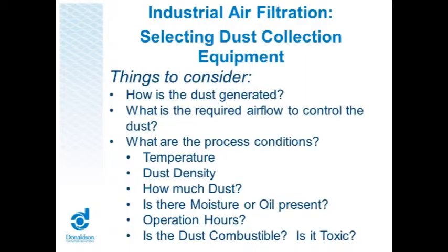It's pretty easy. You've also got the loading, is what we call it, or how much dust are you throwing at it. If I've got a welding process where one guy's doing 5 minutes of welding and 30 minutes of fixturing, that's different than if I've got 5 guys welding for an hour at a time and throwing a bunch of fume at me versus that 5-minute little period of time. So how much am I going to see?